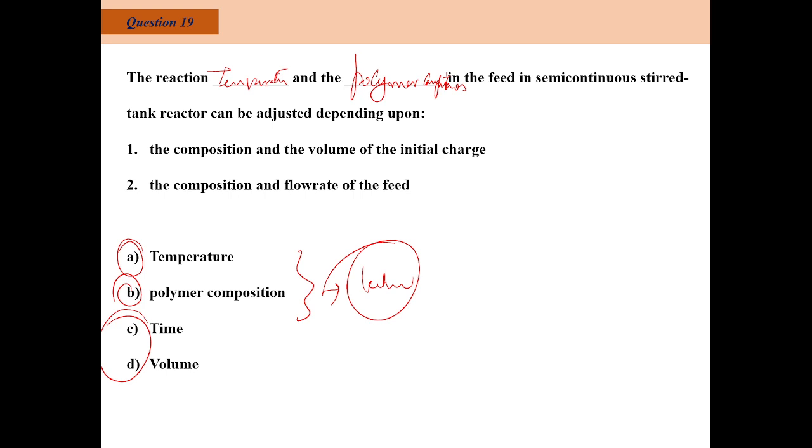As the molecular chain grows, it ends by termination by disproportionation or coupling. But we have some excess free radicals. If I have to kill them, in batch I can terminate at any given point of time by simply quenching with free radical killers. Whereas in continuous, that I cannot do. I have to do it at the end only. By the time, the molecular weight would already have crossed the limit, or will reach that limit, but further, additional free radicals will be there. I have to take care of the quenching further so that it will not propagate further in the storage. For this reason, batch mode is mostly preferred.